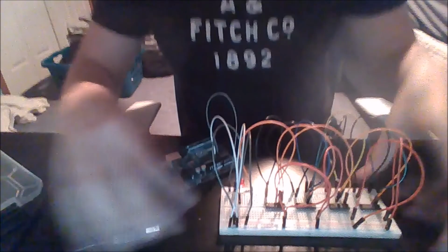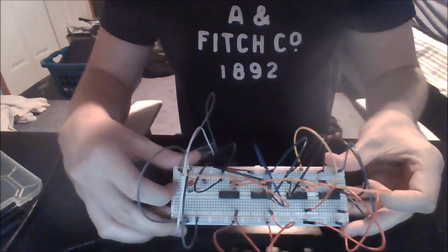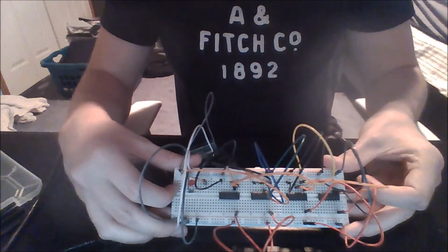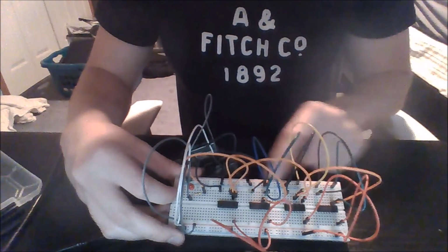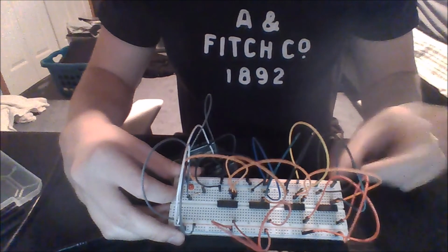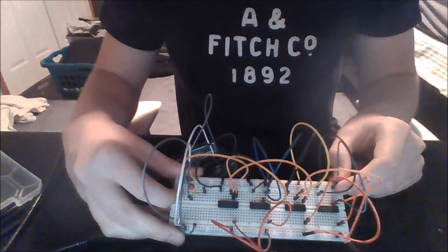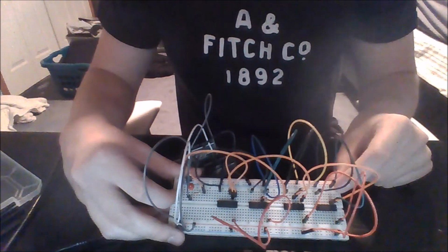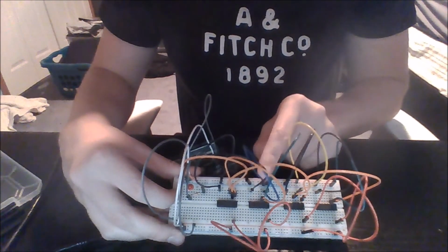If we take a look at this, you can see it matches the Tinkercad creation. If it looks confusing, I would strongly recommend referring to the Tinkercad creation. It'll be much easier to see. So in this instance, I have manually wired all our inputs to either ground or the high setting, which would be 5 volts. So just what I have currently, the green selector wires are high, the yellow A input is low, and the blue B input is high.